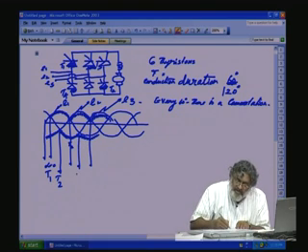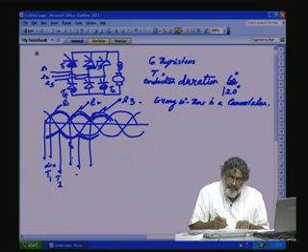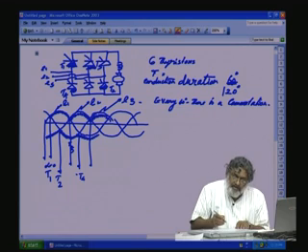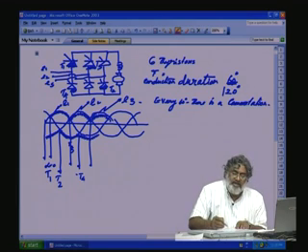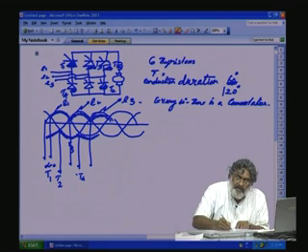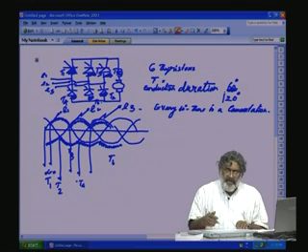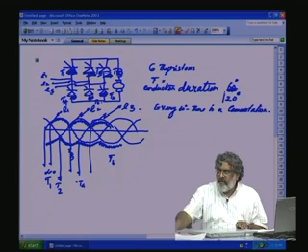At this point T4, T1, T2, this is T4, this is T3. E3 becomes more positive at this point. So, which one has to be turned on? Now, T4 is our next thyristor, we will name as T5 here. Then here E2 becomes more negative after 60 degree, that is T6. This is T6. So, we will again draw the waveform and the conduction duration again we will write for clarity.